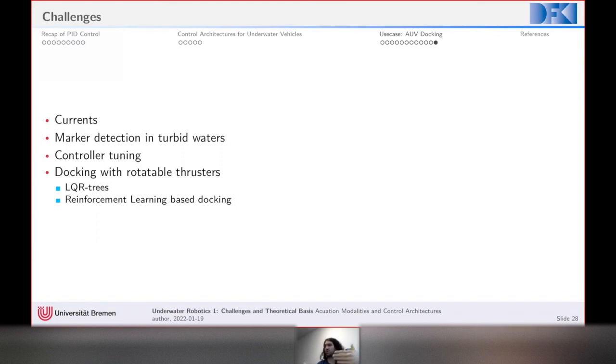So you could switch off all of your motors, and maybe just keep your depth sensor on for a long descent, for example. And then you switch on an altimeter to detect the ground. Whenever you detect the ground, then you can switch your system back on, for example, and do whatever maneuver you want to have, and then go up in a similar fashion.